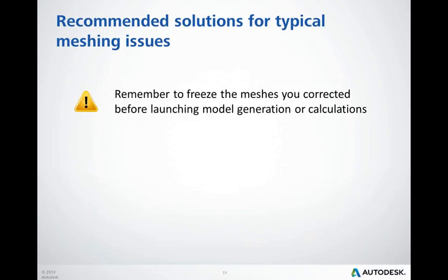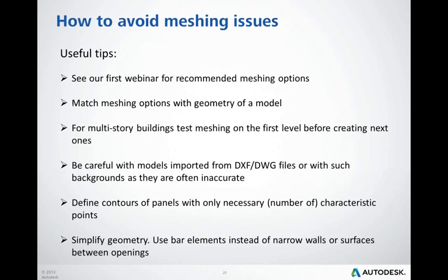And as I mentioned, this is something that you should keep in mind, because if you forget to freeze the meshes that you manually corrected, they will be regenerated and you will have to make all this work from the very beginning again. And let me finish this presentation with a couple of useful tips. Again, I would like to encourage those of you who haven't watched our first webinar to look at it on YouTube and learn how to set the correct meshing parameters to avoid any meshing issues in the first place.